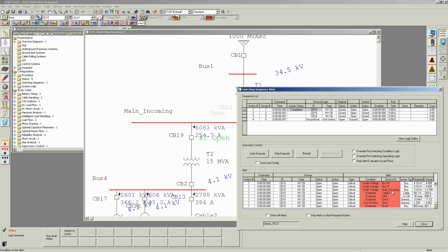For protected devices, what the module will do is it'll check the power flow going through the frame and compare it against the protected device frame size. For the cables, similar. It'll check, say, cable and transformers. It'll check the power flow going through the branch, in this case, whether it's transformer or cable, and check it against the transformer rating or your cable allowed ampacity.